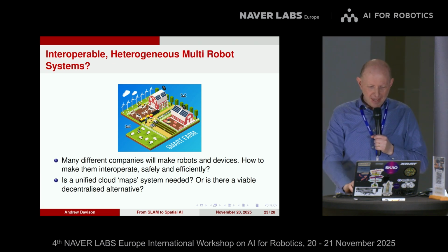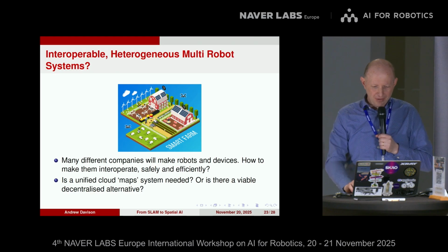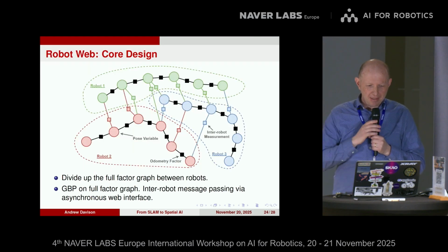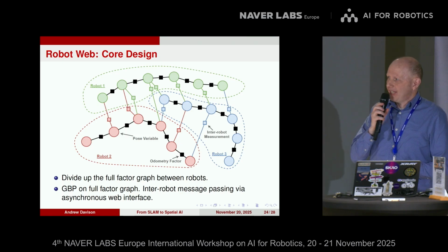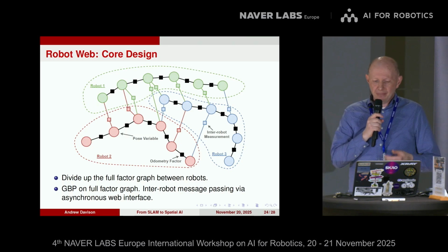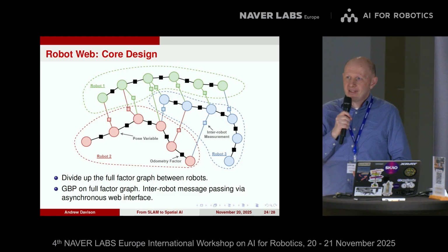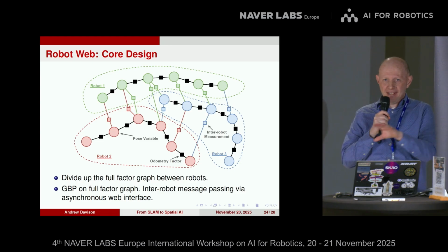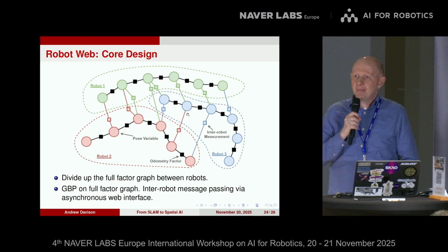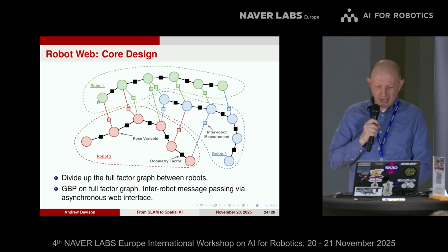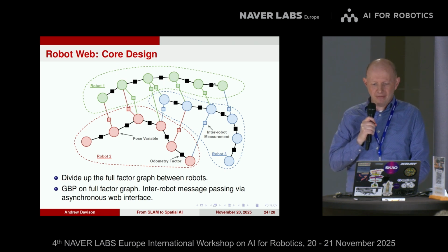So we've been thinking about this kind of problem, and especially initially focusing on a couple of areas. The most important immediate one is localization. How would all of these devices be able to estimate their positions within this global space on the assumption that they have distributed computation? Here we've taken the assumption that we're solving this pure multi-robot localization problem. We have 3 robots in this example. The things that we're trying to estimate are the positions of each of those robots over a set of time steps.